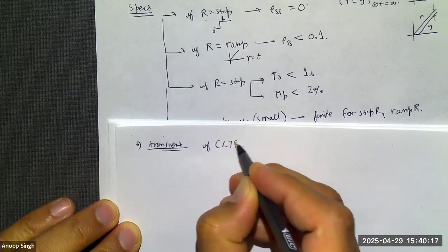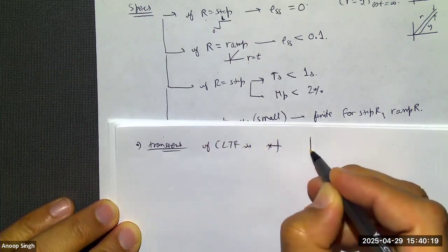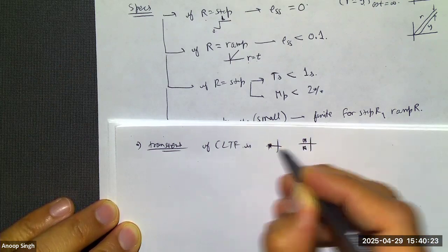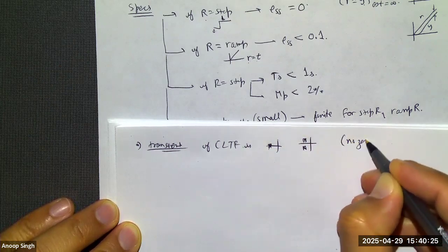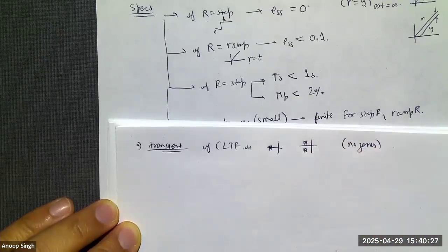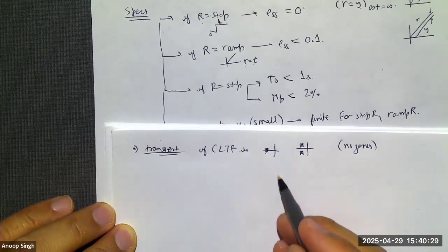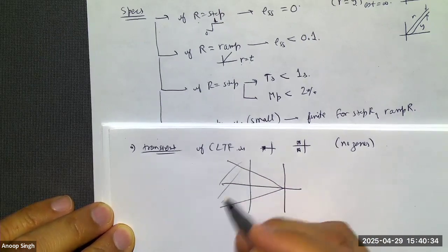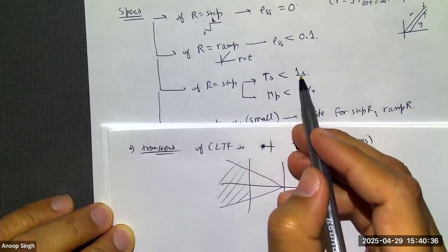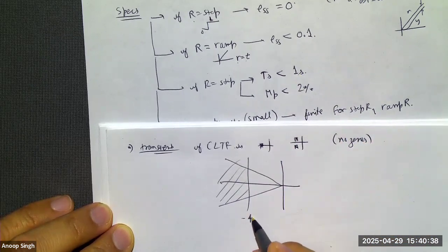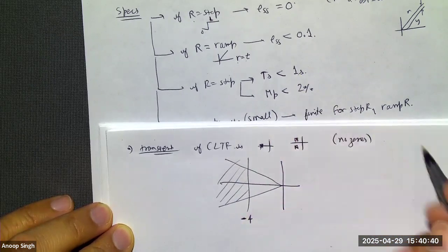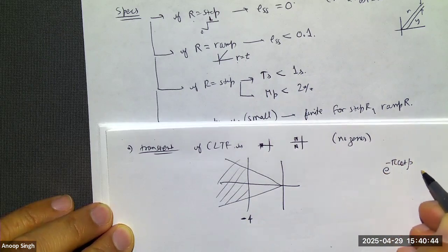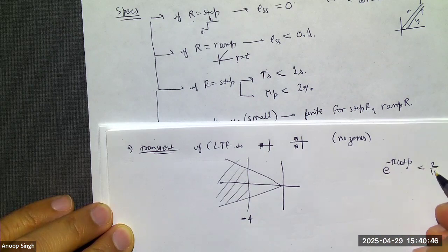So if the closed loop transfer function is a one pole or two complex pole system, if this is how your closed loop system looks like and has no zeros in it, then we have done this like a gazillion times. This will basically boil down to the closed loop poles being more negative than -4. And the overshoot, we have a formula for it: e to the power minus pi cotangent of the angle.